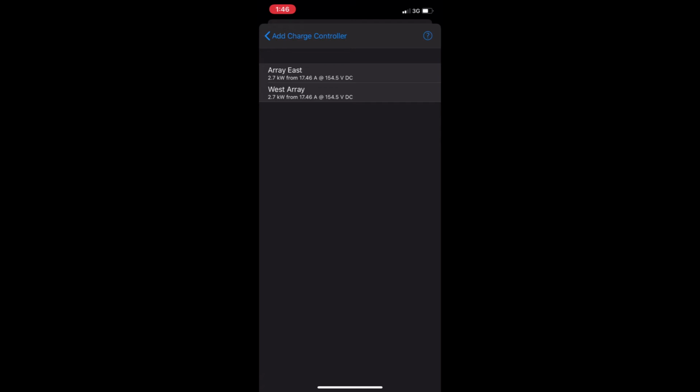Basically, they are mini charge controllers / regulators that deliver a constant voltage from each panel and vary the amperage instead, which stops an underperforming panel, whether by shade or fault, from dragging the whole array output down. If your panels will receive a lot of patchy shading, or you want to be able to monitor each panel's performance to detect faults or underperformance, you may want to invest in optimizers to maximize your solar output. For this building, we will not be using optimizers, so I'll go ahead and connect the east-facing array.